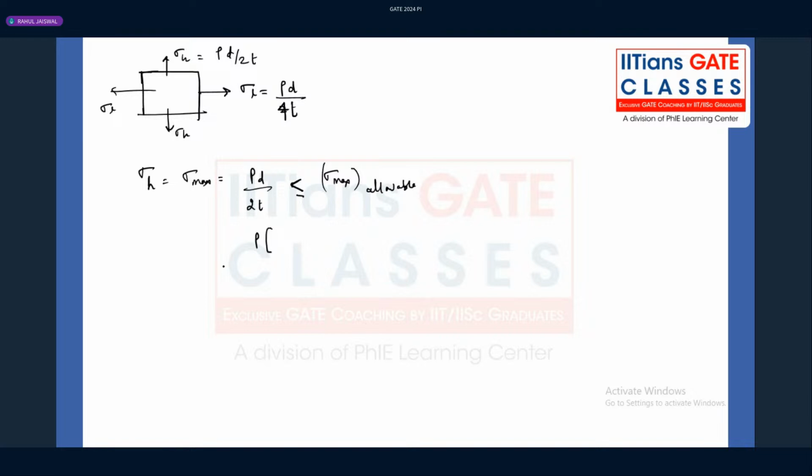So what should be the P value, considering the maximum normal stress? What is the D value? D value is 2000, over 2T, should be less than or equal to what? Maximum allowable value, which is nothing but 100. What is the P value, guys? It should be less than or equal to 100 into 2 into 4 over 2000. This value should be 0.4 megapascal, considering the maximum normal stress.